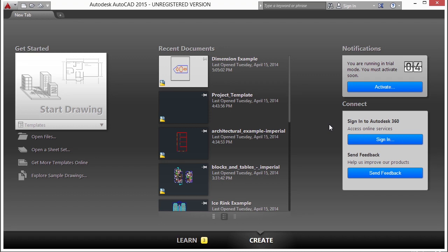Just as the display features of objects are controlled by layers, dimension styles control the display features of dimensions. Dim styles also control various dimension settings. Now, there are several hundred settings, and that's not an exaggeration, of system variables for dimensions alone, not to mention the other system variables for regular AutoCAD. Styles will help you control and manage them.